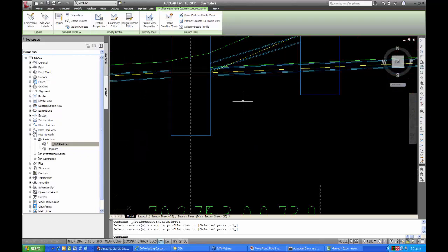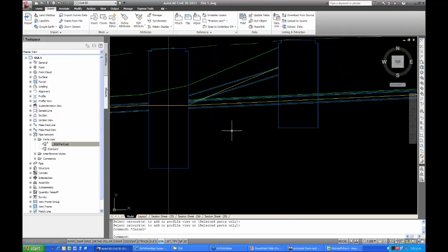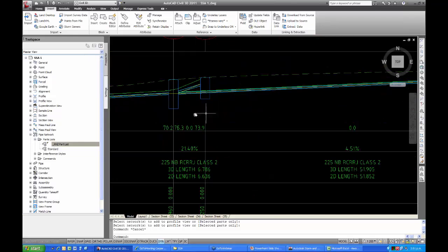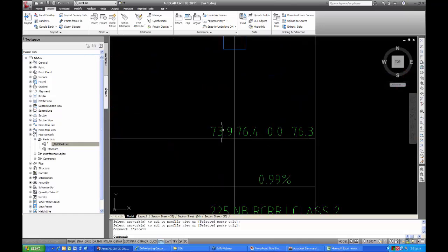and it just drops the entire network back into that profile. But what it does do is bring through, if you have a look on the screen there, those two lines, the hydraulic grade line and the energy grade line. Energy grade line is the green one, hydraulic grade line is the yellow one, and it's also getting those reported. If we have a look down here in the bands, our hydraulic grade line is being reported in the pipe style, that is the ANZ pipe band style.